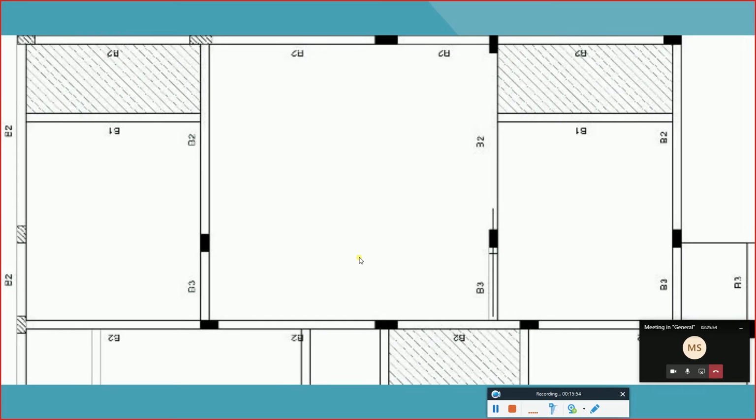Now to explain this scenario, we have said if we are having a large area, which is either a mosque or a majlis, for example, a majlis or mosque, normally we prefer to use inverted beam or other systems like waffle or ribbed slab. If we have a large area and we want to design it, we can see that this slab is a little bit big in the sense that it has a bigger length and a bigger width. If we design it regularly, as a solid slab,